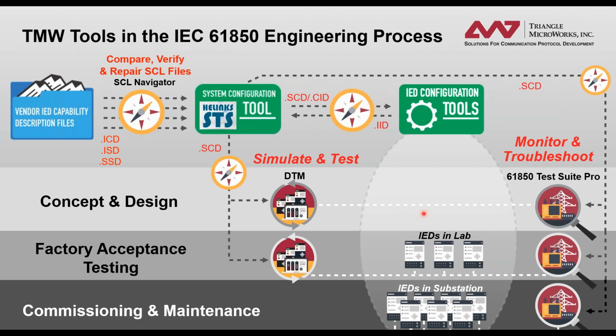Down here in this diagram, this section we'll be looking at in the next webinar. As I mentioned, our Test Suite Pro tool allows you to help verify this, and the DTM simulates it. So as you've got this design together from the SCD, we can simulate that in DTM, test the system configuration with Test Suite Pro, and then move on down into implementing it with the real devices as those become available. So that in a nutshell is the 61850 engineering process.